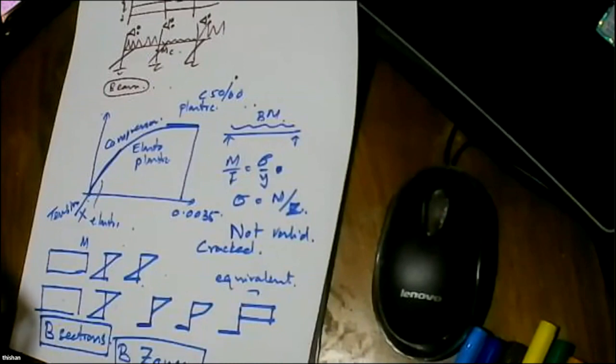For example, a 1200 pile can usually carry a 6500 kilonewton load, but it is now carrying only 4200. A 1500 pile can generally carry 10,500 kilonewtons, but on this particular site it can carry only 6500 kilonewtons when you do all the calculations according to the geotechnical engineer.